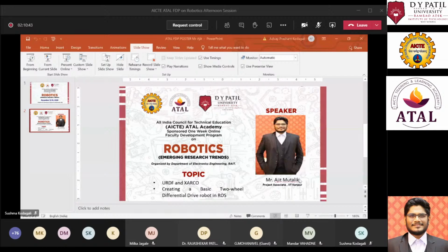So here in the caster wheel code, what I have done earlier is I have combined the caster wheel with the cube itself. So here I have just mentioned the caster wheel collision model and the visual model. Since the caster wheel doesn't do much and is just a collision model, we don't need to define further its mass and how it should be inertial. We can just skip that part as well.